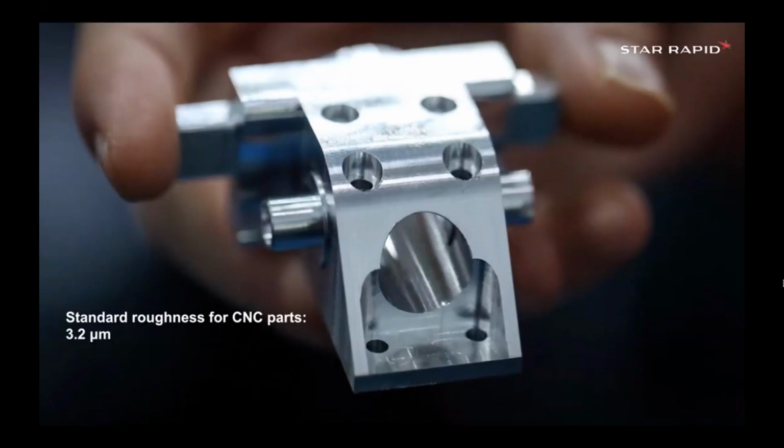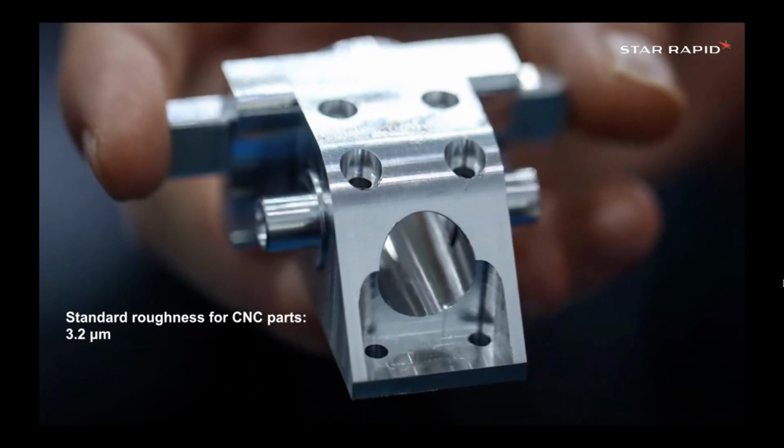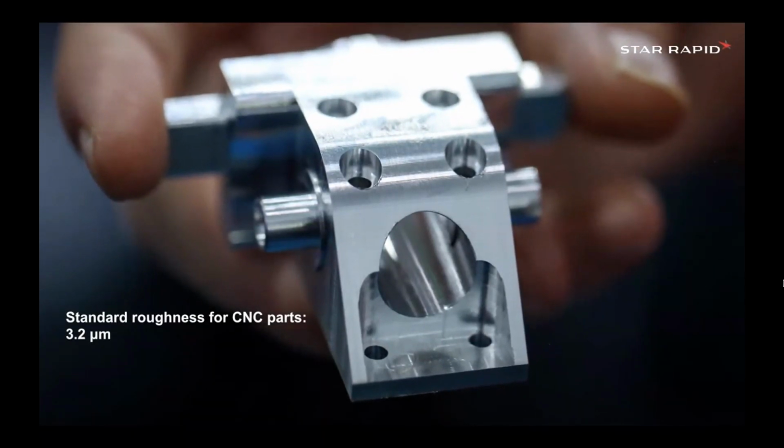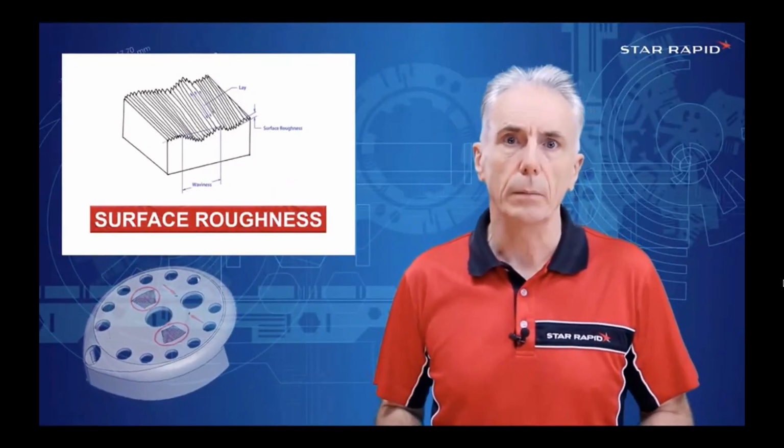At Star Rapid, our standard roughness for CNC machine parts is Ra 3.2 microns, but we can do as fine as, for example, 0.2 microns on a CNC machine. But it might take 10 times longer and cost 10 times as much. So please try to stick to no finer than 3.2 microns unless you need it.